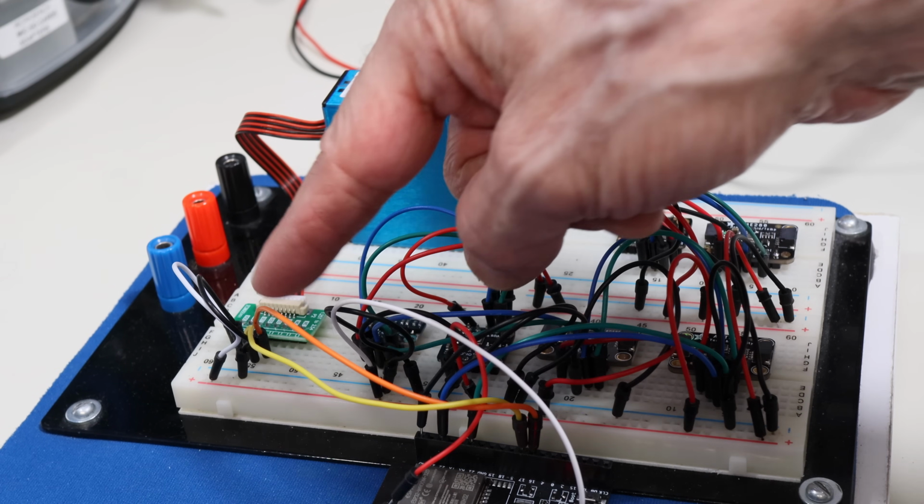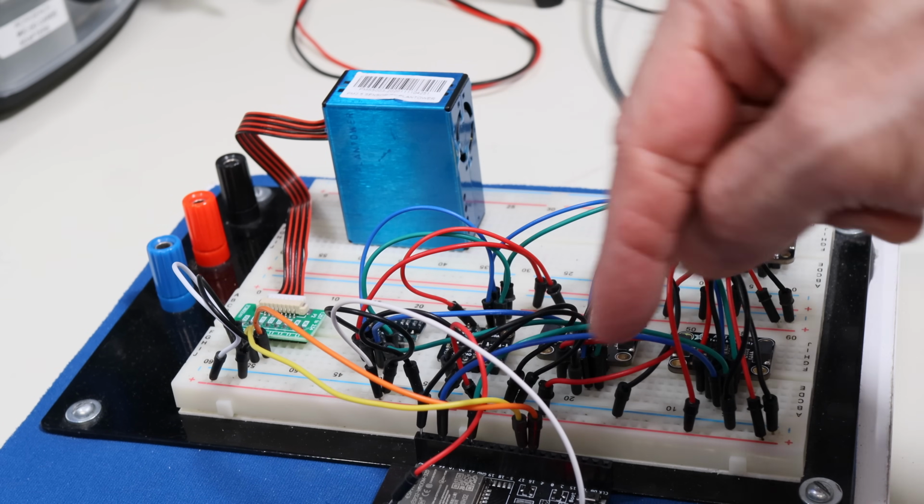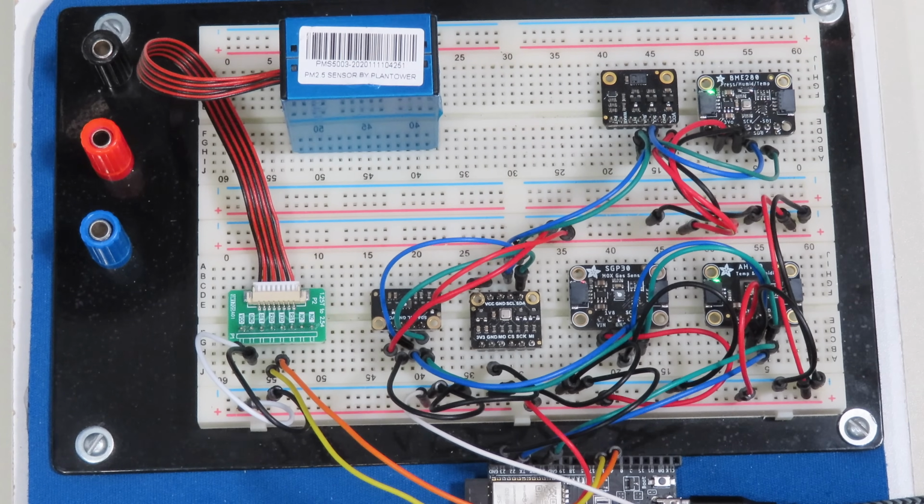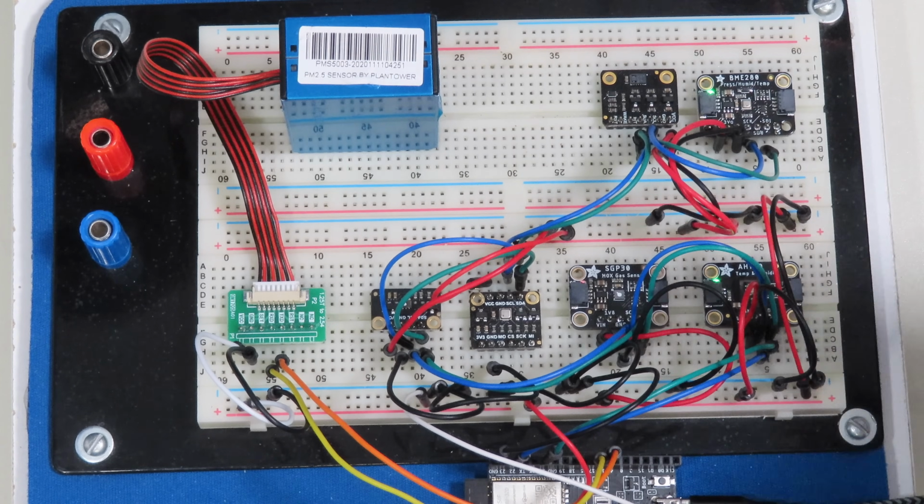I've got the output and input of this connected to an ESP32 using one of the UART ports because this is a serial device. Now there are a number of libraries that you could use in order to use this device. However, I had a problem with a few of them, specifically the Adafruit one, in which it would run and then lock up after about half a day. And at first I thought my sensor was bad, but actually it turns out after Googling I found it was a common problem. And it's because many libraries are not looking for a specific byte that sometimes comes from the device, and it kind of messes up their code.